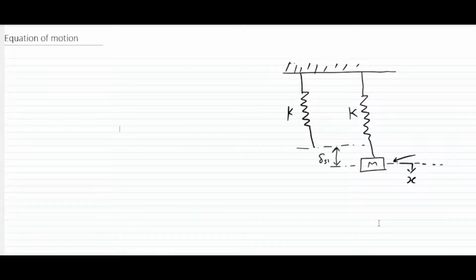Today I will be showing you how to derive the equation of motion for a single degree of freedom undamped free vibration. First, let's assume a weightless spring, where one end is free and one end is fixed. So this spring is at the steady position. Now at the free end, attach a mass M. Due to the weight of the mass, the spring will be stretched and deformed by delta st.